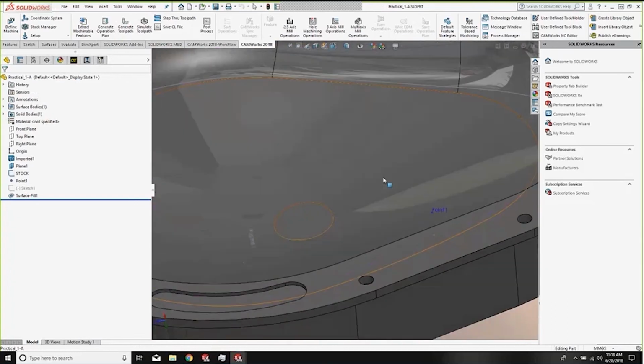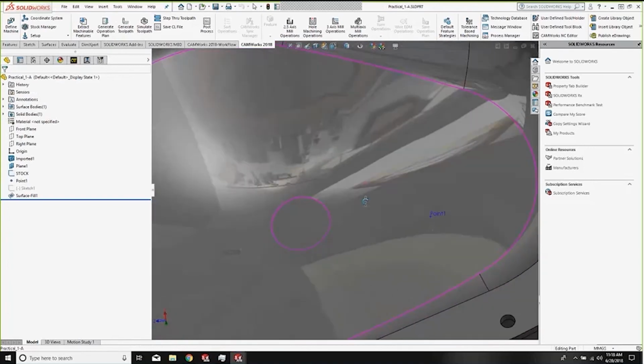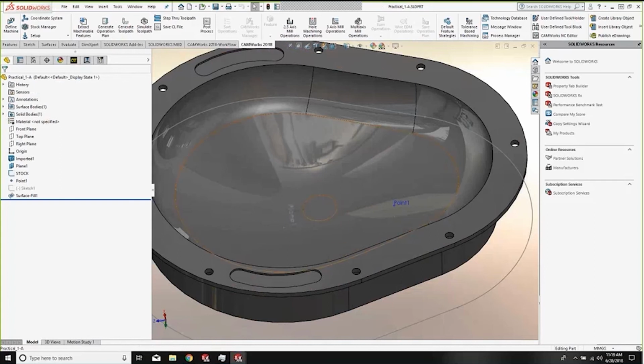It's not completely flat. There's actually taper. It's minimal, but there's actually taper. So depending on the cut direction, it's going to limit the tool motion that I can get. If I want to come down here and maybe try to spiral once I get to the bottom, the problem is, what if this is running uphill and downhill? Well, then that turns it into a constant Z. And that's going to force me into getting a lot of retracts. And every time we get a retract, that requires a plunge move back into the cut.